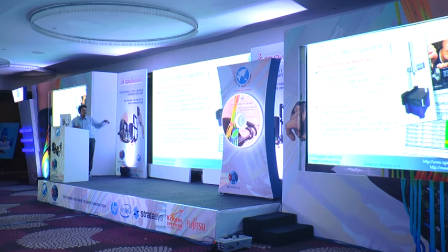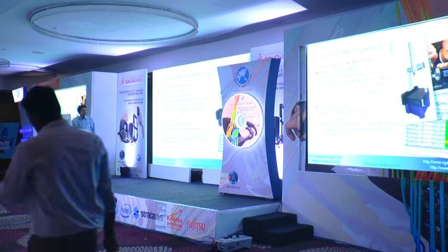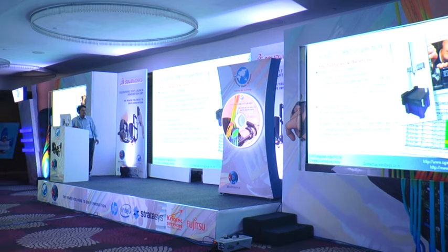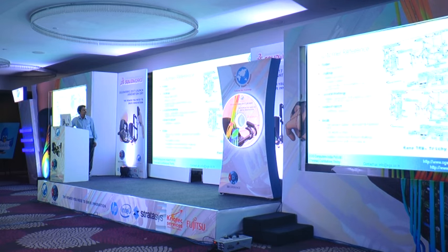You can measure the input value directly. You can use digital instruments. You can also use CMM. And you can easily highlight the dimensions in green, red and yellow based on the results. So this is a project we did for Rani TRW Trichy, where they gave their 2 drawings, a nil revision and an A revision. We did both drawings with the balloons, and we have proposed this solution.